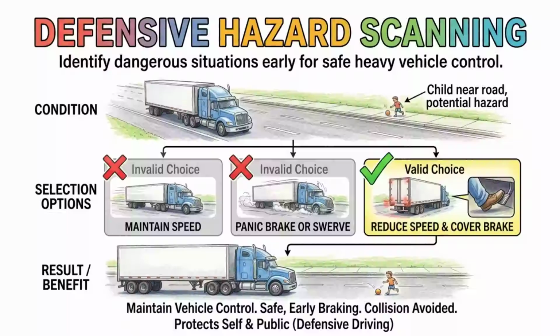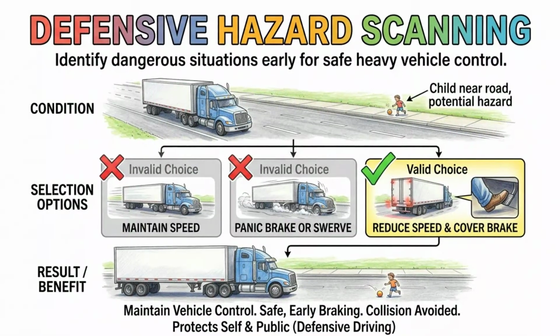Extreme heat also causes unique mechanical hazards that you must monitor closely. When driving in very hot weather, you need to frequently check your tires because heat causes tire pressure to increase. If a tire becomes too hot to touch, you must stop driving and let it cool down, or it could blow out violently. You must also keep a close eye on your engine temperature gauge to prevent the engine from overheating. Never attempt to remove the radiator cap from a hot, pressurized cooling system, because the boiling coolant can spray out and cause severe burns.